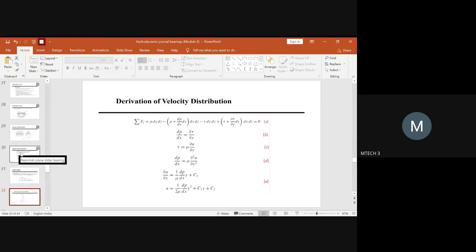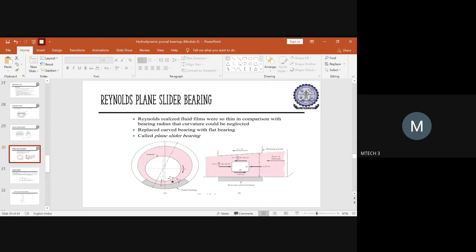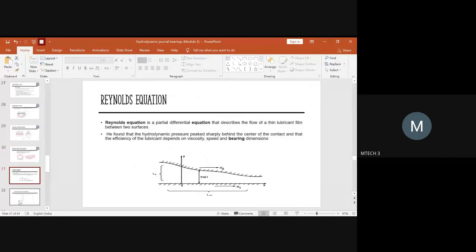After that, you have to give the values of the shear stress force. This is coming in the positive direction. So you'll write plus tau, open the bracket, write tau plus dou tau by dou y into dy, close the bracket, again write dx into dz. Okay, so that will be the positive direction that you have to write.